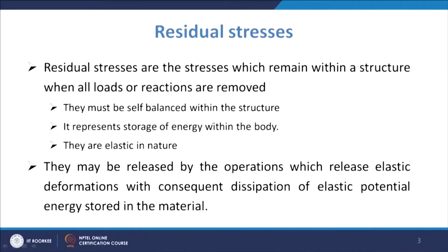So, coming to the residual stresses. Basically, residual stresses are the stresses which remain within a structure when all loads or reactions are removed. The forces which are there are balanced within the body. So, they must be self-balanced within the structure, in the absence of external forces causing them.